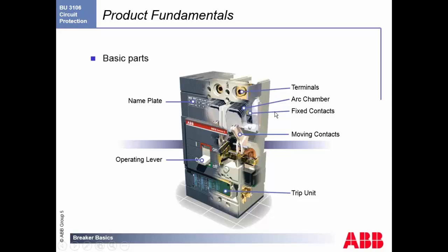An arc chamber. Now one of the things that we know is that when you open up a current switch or a breaker, you do have an arc going between the two contacts. We have moving contacts and fixed contacts. As you open up, you will experience an arc flash. We do take that into account, and we have these arc chambers that are designed specifically to make sure that the arc flash is extinguished as quickly as possible without any damage to our breaker.